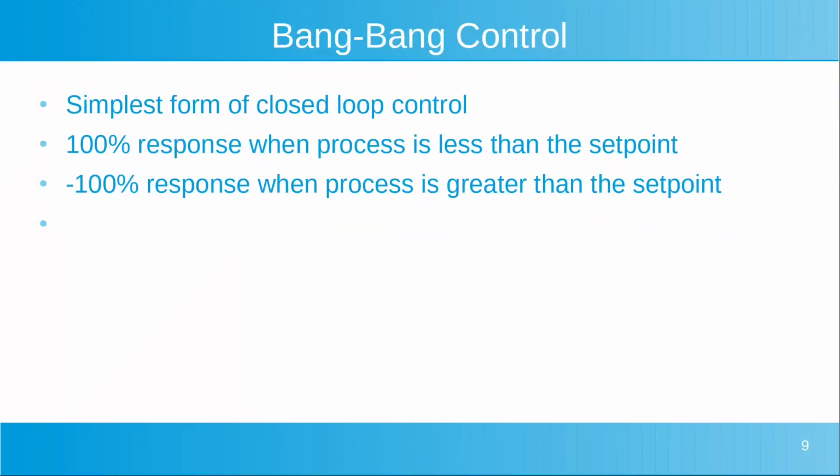Bang-bang control is the simplest form of closed-loop control. It produces a 100% positive response when the process is less than the set point, and a 100% negative response when the process is greater than the set point.